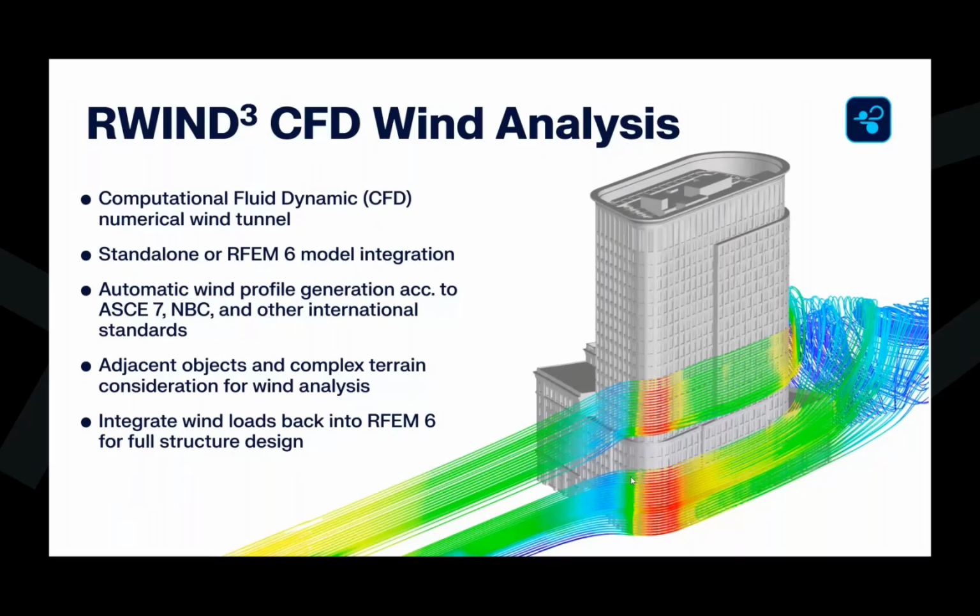Now, our RWIND can certainly be used as a standalone. We have architects, for example, taking advantage of this. It's not necessarily just for the structural engineer, where you could import in an IFC file, because all that we need is the geometry here to determine what these wind pressures are. But the powerful thing is integrating, of course, with RFEM 6. So we can automatically send our structure from RFEM 6 into RWIND, calculate the wind pressures, and then bring the wind pressure information back into RFEM 6.